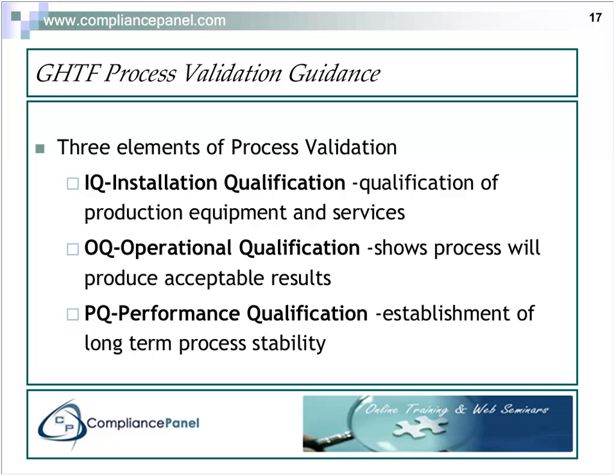The third and final phase is performance qualification, and that's the step where we establish long-term process stability. We're going to run it all shifts, all days, and that sort of thing, the way that process would normally operate. And we're going to demonstrate that it will produce product that meets the requirements day in and day out.